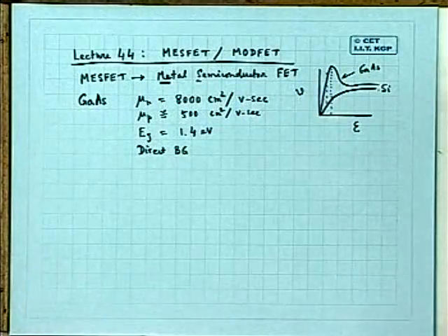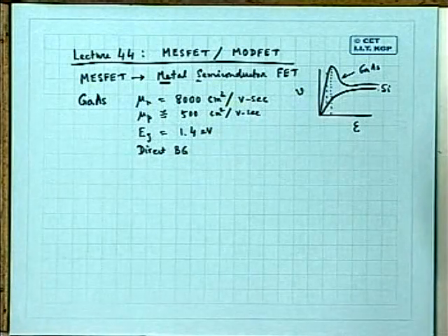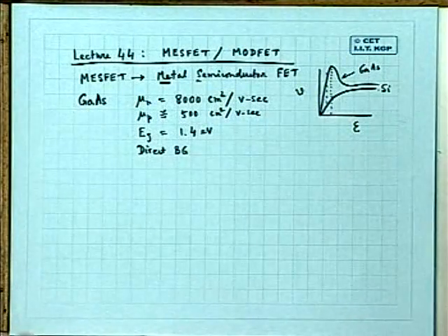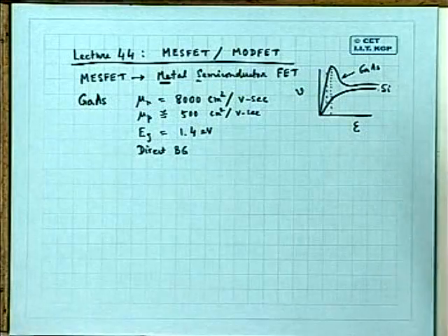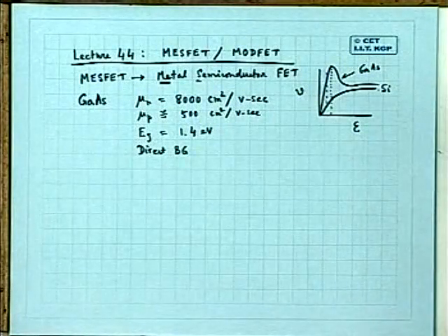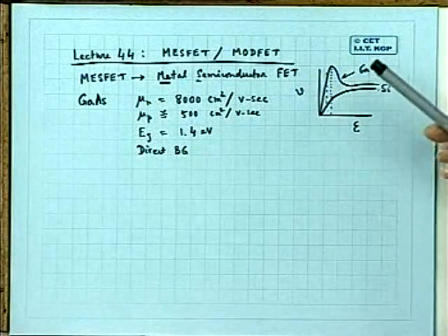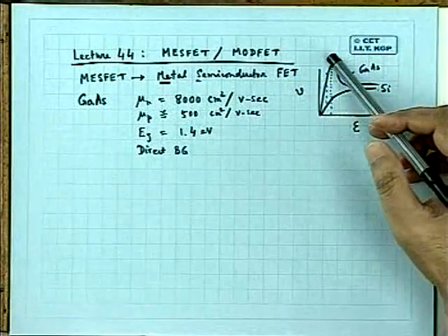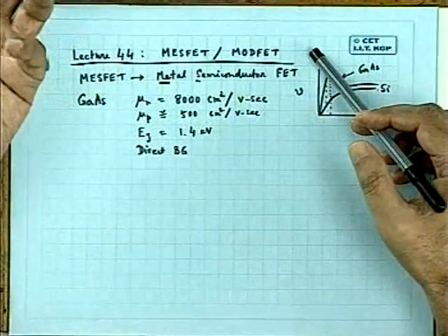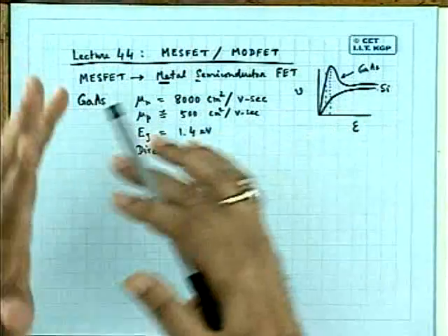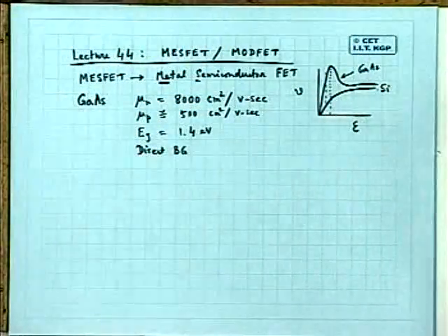But slowly the MOSFET technology became a reality, and in the 60s and 70s particularly, MOSFET started growing like anything. It became so important because of, as you know, the low power dissipation, high input impedance, dynamic memory, dynamic logic, and all this, so far as VLSI and logic implementation is concerned.